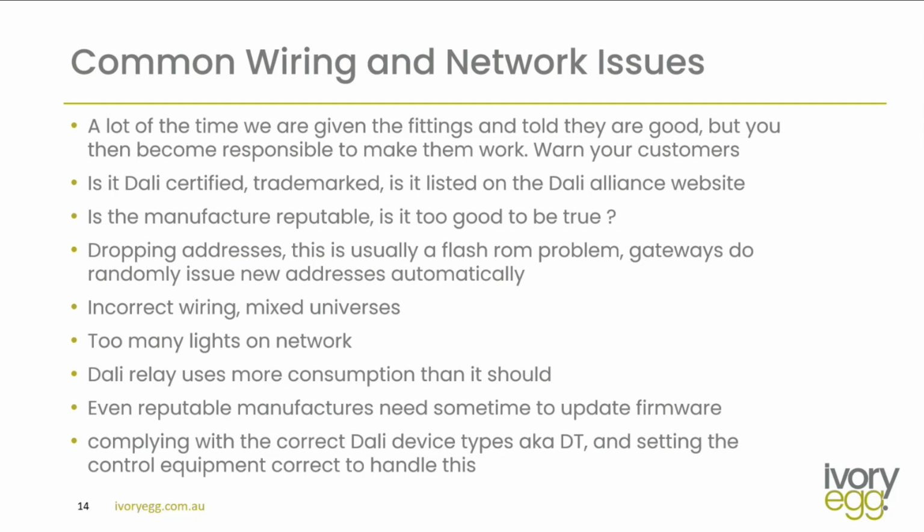A lot of the gateways will warn you if there are too many lights on the network, and this is a really hard one, especially for consultants. Under the DALI standard, there is the ability for 64 fittings. I can tell you, if you have any experience with the DALI network, for the maximum amount of fittings I've heard some people say 50, some say 55. There's a good reason for that. DALI is a really slow protocol and it's a polling protocol, so we want to leave room and headspace and bandwidth for DALI to operate correctly. But more importantly, if a customer is unaware that their DALI network has 64 fittings on it and they try to add more fittings, it's going to kill it.